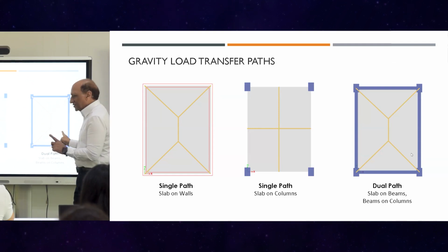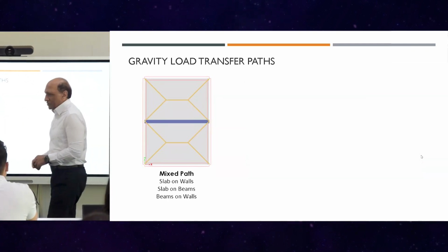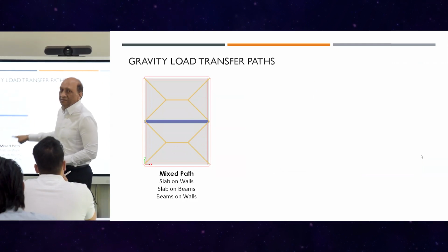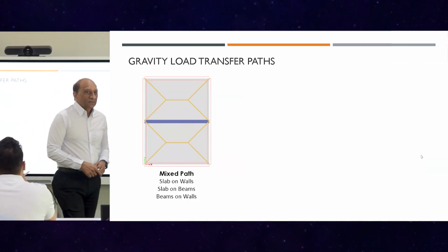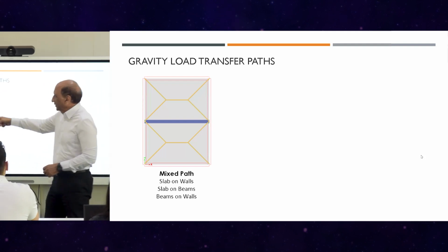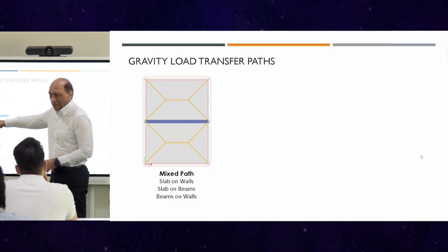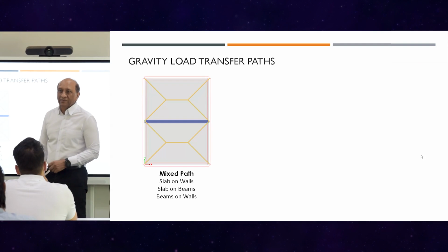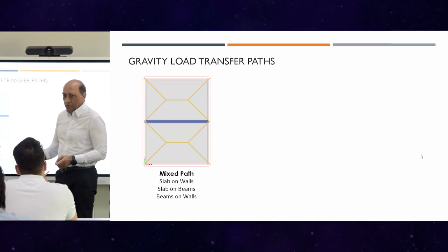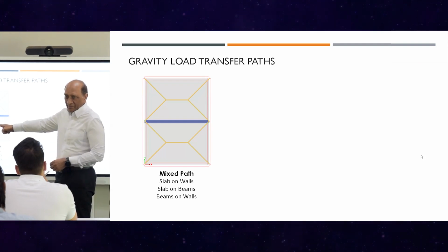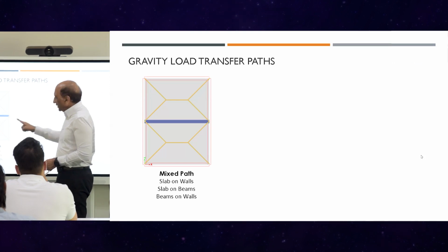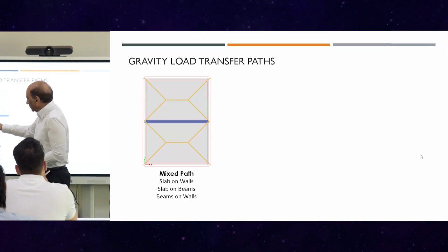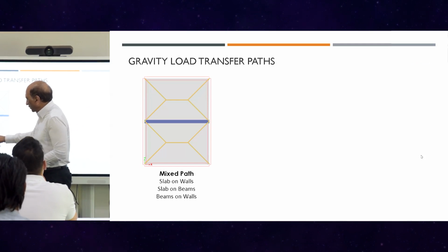Okay, let's discuss this further. Another question. Now we divide this panel into two panels by putting a beam on this one, which means that now the load transfer geometrically should be looking like this, based on that previous slide: this portion will go to the beam, this portion will go to the wall, and so on.